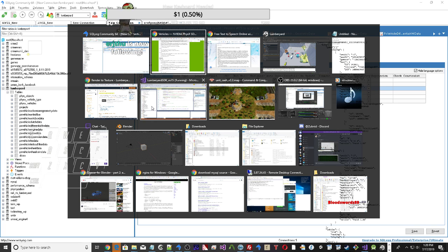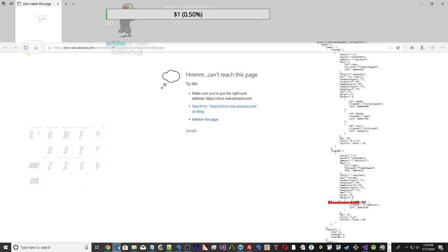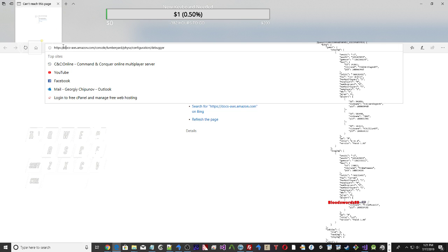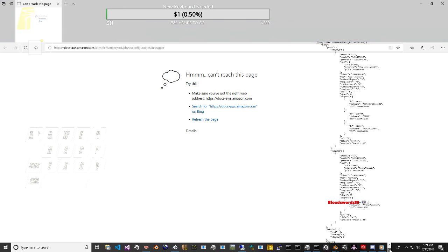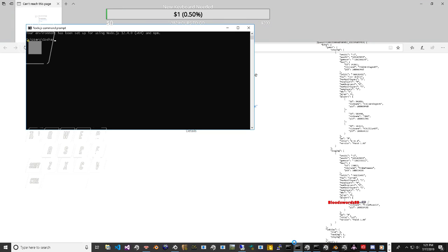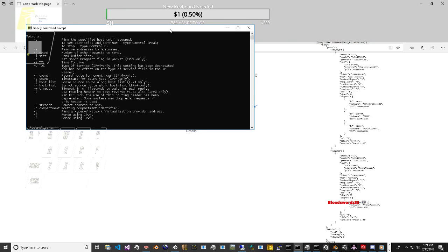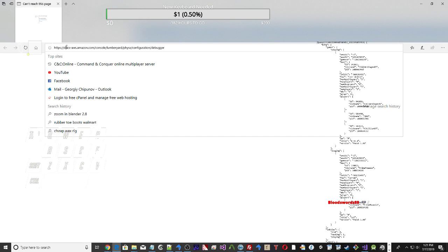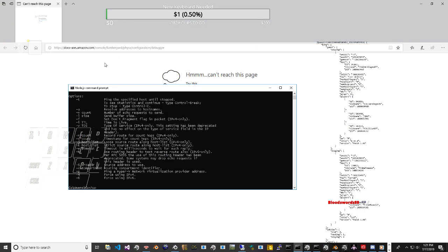Introduction to Vehicle Creation. The following pseudocode illustrates the basic process of setting up a PxVehicleDrive4W instance. const PxU32 numWheels = 4. PxVehicleWheelsSimData* wheelsSimData = PxVehicleWheelsSimData::allocate(numWheels).